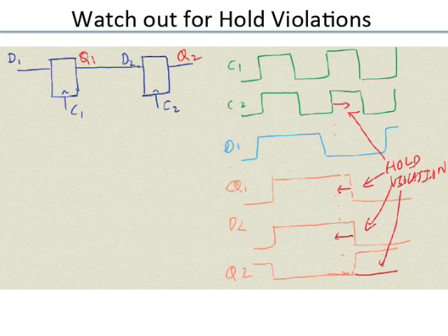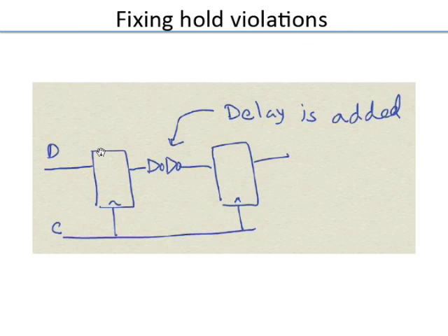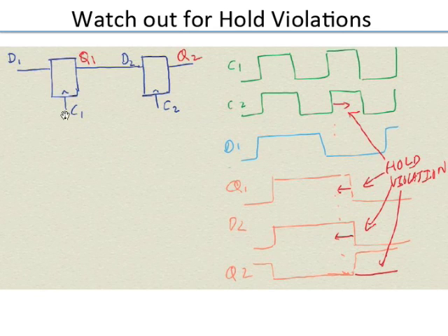Now, one of the important things you need to worry about when you have shift registers is hold time violations. Let me just explain. We saw the setup time issue, right? Setup time means, when a clock edge happens, remember, these are edge triggered flops. That means a positive edge here. If I put a bubble, it becomes negative edge triggered. When a positive edge happens, I capture whatever was there at the D input and put it to the Q output.